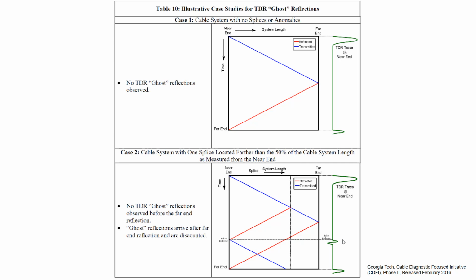So the oscilloscope immediately records that. So this is the recorded signal on the oscilloscope, the green signal on the right side. This reflection is due to the joint, and the transmitted wave is continuing and reaching the far end. From there it is again getting reflected. So this reflection is of the far end actually. It will come back like this and reach here. So you can see this kind of waveform which is observed here.